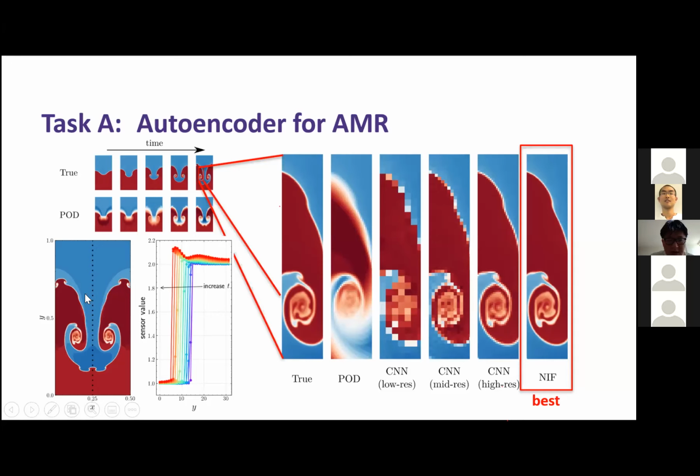And then we use these 32 sensors as our input to determine which flow state the flow is currently experiencing. You could use convolutional neural networks or any other techniques, or maybe for your problem, you want to randomly choose some sensor points. As long as the number of sensors is larger than the ground truth dimensionality of the flow, then you are okay.